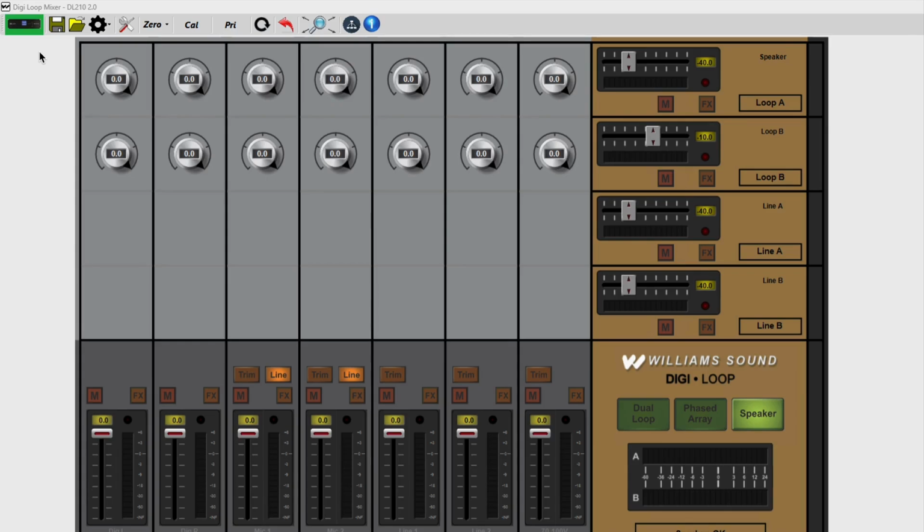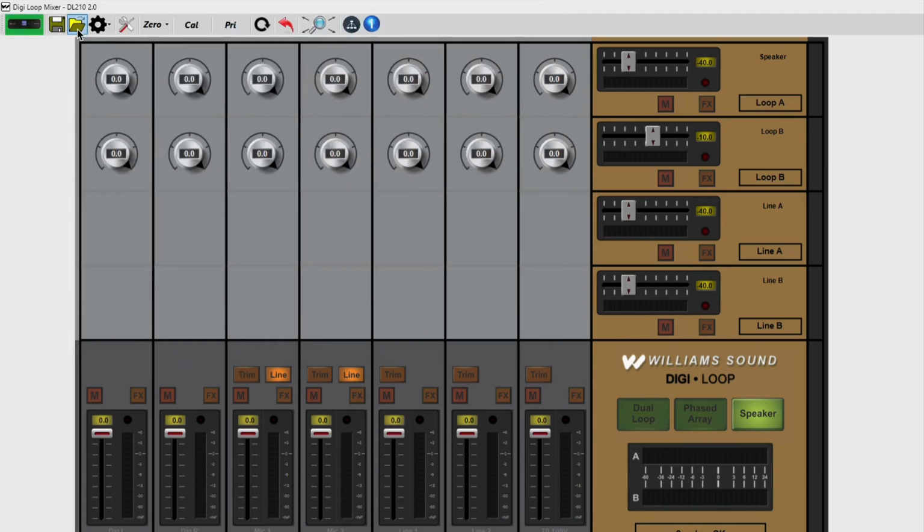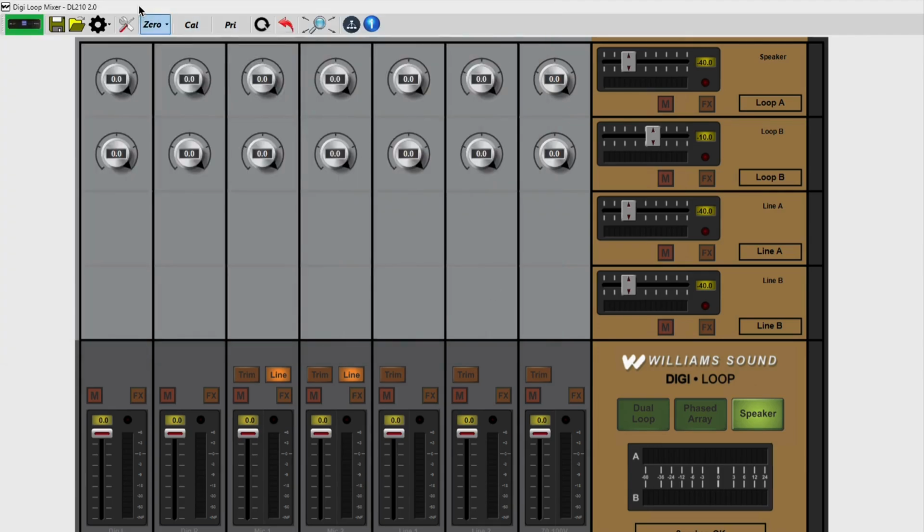Save, Open, and Presets icons. The small disk icon allows you to store the current amplifier configuration. The folder icon allows you to browse to a previously saved configuration for loading into the amplifier. The small gear icon allows you to browse to factory preset configurations for loading into the amplifier. These presets serve as a basic starting point to set up the amplifier. Please note, the amplifier will still need to be calibrated and commissioned using a field strength meter.